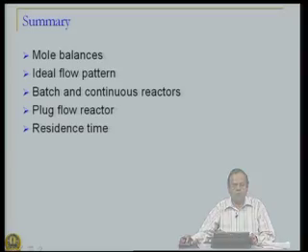With this, we will come to the conclusion of our design equations. Essentially, what we saw in this lecture was how to do a mole balance on a reactor, and we considered only ideal reactors. Ideality depends on the flow pattern inside the reactor, that is, whether it is a well mixed reactor or whether there is no mixing in the axial direction, a plug flow reactor. We have different kinds of reactor behaviors. We also have different types of reactor operations: batch, continuous.